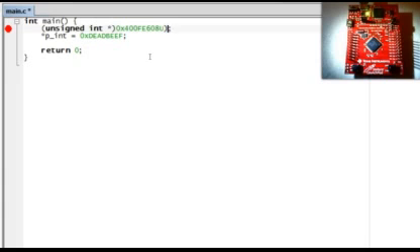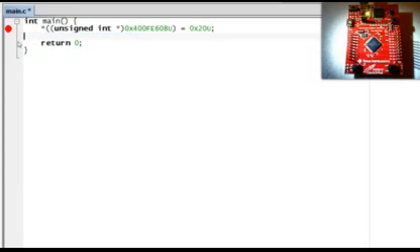Enclose the whole pointer cast in parentheses and notice that this whole thing is a pointer to unsigned int. If so, then you should be able to dereference this pointer by means of the star operator, just as you see in the line below. Now you can write to the pointer. As you recall from the experiment in the debugger, you need to set bit 5, that is hex 20, into this register. The value should be unsigned, which you indicate by the U suffix. Get rid of the no longer used pint pointer and check if the compiler likes your code by pressing F7.